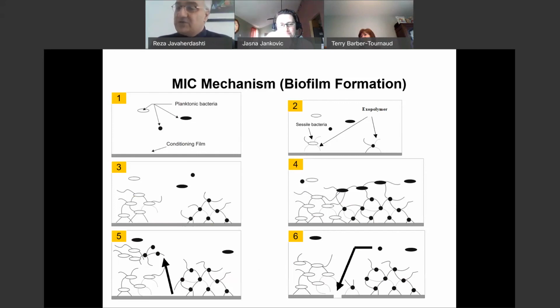In seawater, you already have a lot of ions. And that's why in industry, one of the most challenging corrosion questions is to keep demineralized water as ion-free as we can. Most of the time, this is not possible because when this demineralized water comes into contact with air, it starts to dissolve carbon dioxide, which will produce a weak acid, and then this weak acid will go through a lot of chemical reactions. The end result being that you will get corrosion.